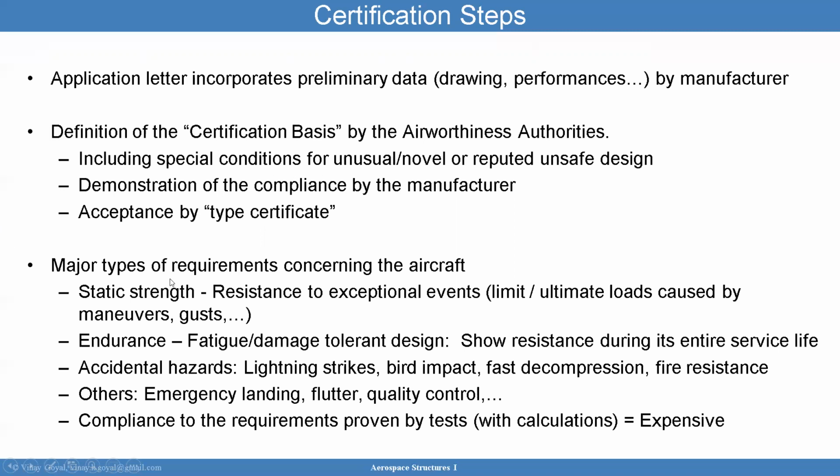I covered this already, but for major types of requirements concerning the aircraft, you have to look at static strength, which is resistance to exceptional events, and endurance, which includes fatigue and damage tolerant designs. They have to show resistance of the aircraft structure against any damage induced during the service life. You also have accidental hazards like lightning strikes, bird impact, fast decompression, and fire resistance. And then you have other things that need to be looked at, like emergency landing, flutter, and quality control.